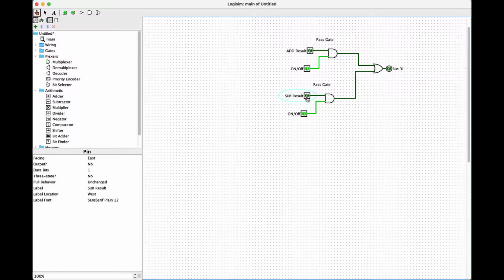We're just going to assume that they will only turn on one of these pass gates as a result. So what we need to do next, after you minimize your adder and your mux, is place down 9 of these pass gates and then do their operations.